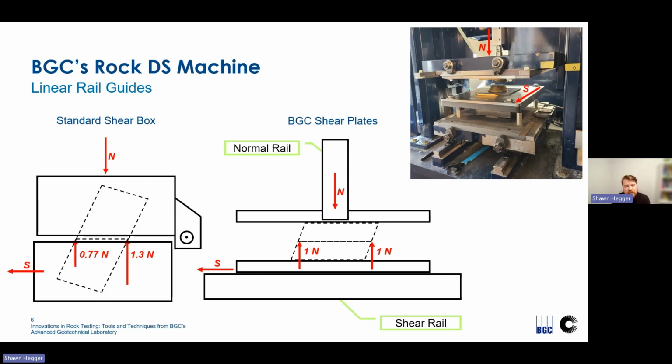Fundamentally, the direct shear test is intended to simulate planar sliding along a joint surface. At the scale of the joint, the freedom to rotate in any direction is severely restricted, and so should the apparatus that's simulating these conditions. So the figure on the left illustrates a typical conventional sample mold setup, which incorporates a pivot point on the top to prevent lateral movement.